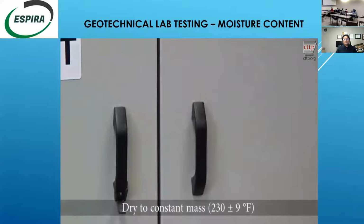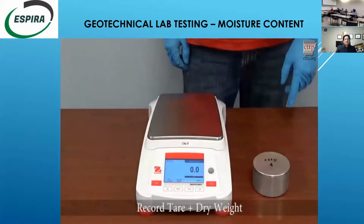Dry the sample to constant mass at a temperature of 230 plus or minus 9 degrees Fahrenheit. Constant mass means that the change in mass is less than 0.1% after 1 hour of drying. If the sample contains gypsum or has a high organic content, dry it at 140 degrees Fahrenheit or use vacuum desiccation. Remove the sample, container, and lid from the oven.